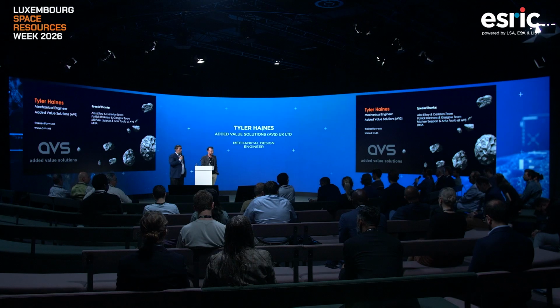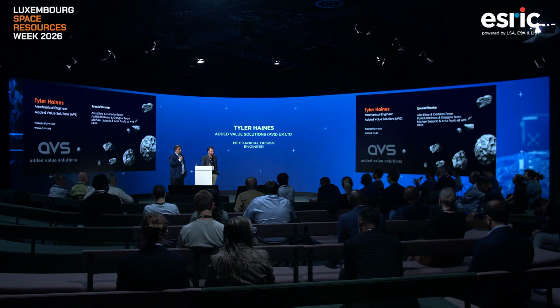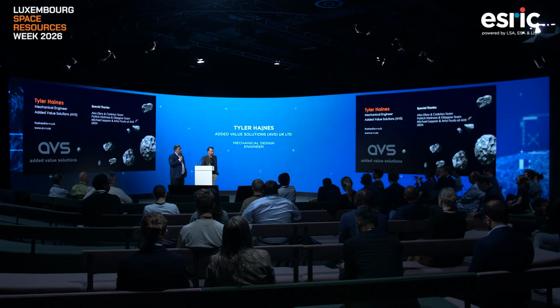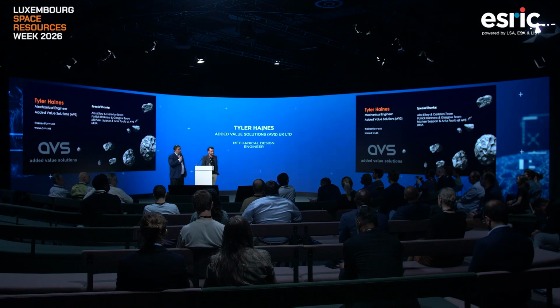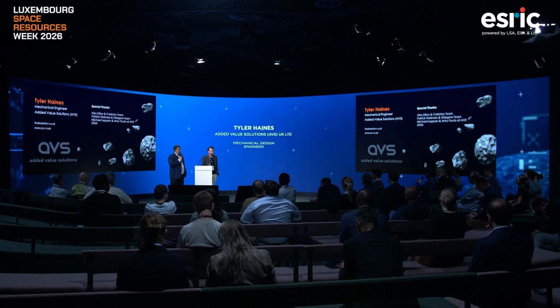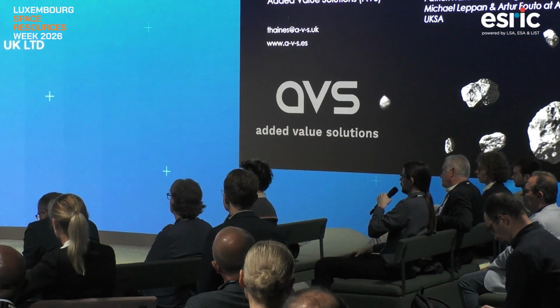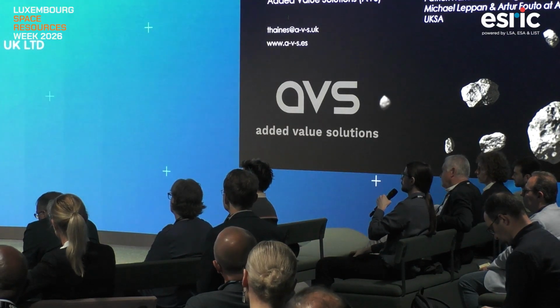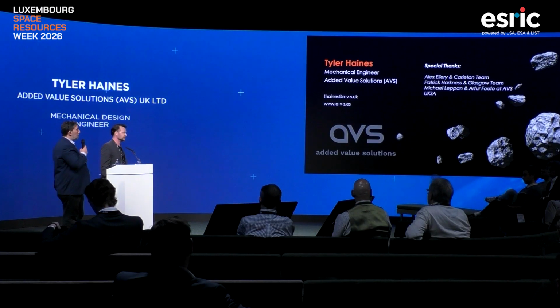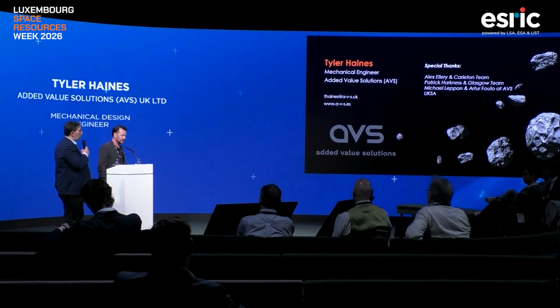I have one question about your electrode setup. If I understood it correctly, you've got the spring in there that is pressing down on the cathode. That's correct. And that will be submerged in the electrolyte and subjected to the electrolysis temperature. So what kind of material would you imagine for that spring? Because we're using a single-shot device, we feel that some sort of nickel superalloy should be more than sufficient, at least to survive that process.